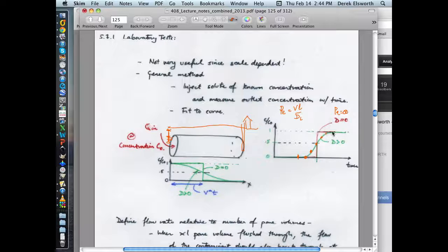Of course, you wouldn't have this curve to be drawing on. You'd just be drawing a series of points with time. But rather than drawing these points with time, I suppose what you'd want to do is draw them as a function of residence time distribution. And so, as you just so rightly said before, your time would just be modulated by your advective velocity, which hopefully you could measure. If you know what the Darcy velocity is and the porosity, you could certainly measure the advective velocity.